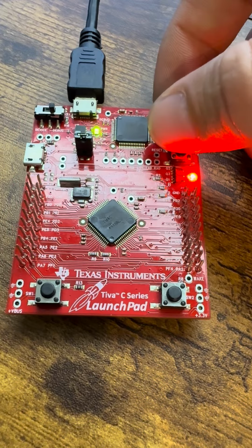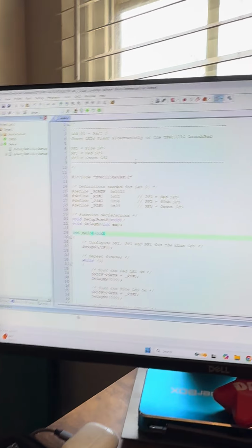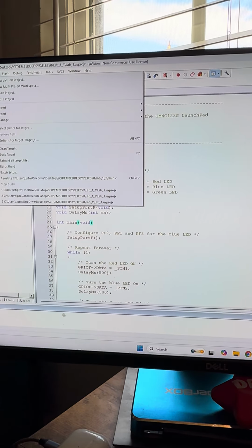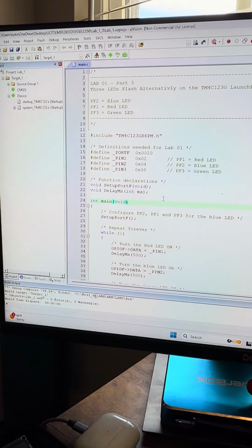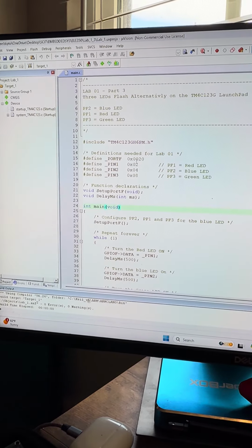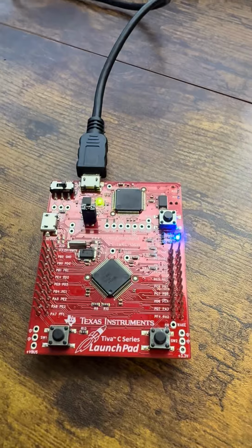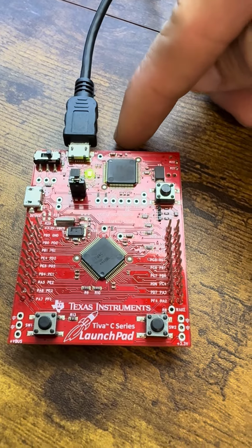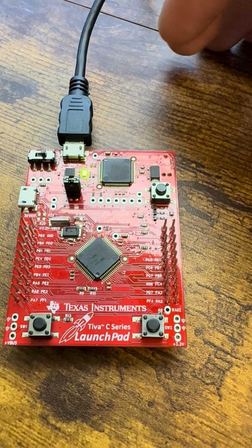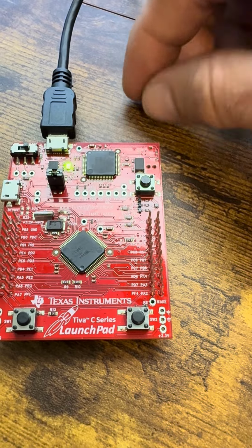Okay, so I just opened up that third file. Okay, I'm going to build the targets, which is going to check all my code for any errors or warnings. Okay, everything looks good. Then I'm going to download that into the microcontroller right now. You see, boom, those just shut off. So now that new program is in there. The clock is reset and everything is ready to go.